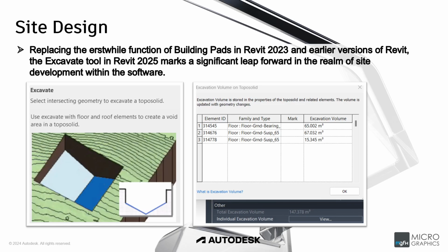You can add multiple points, and it will also display quite neatly in a scope box or in a section view to see how the layers underground would work. The topo solid itself can also be edited, and multiple different sub elements can be created if you wish to show your hardcore filling and those kinds of things.